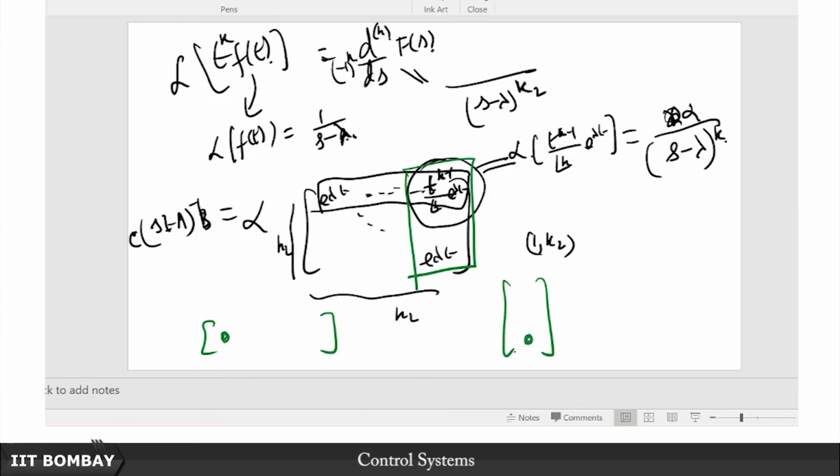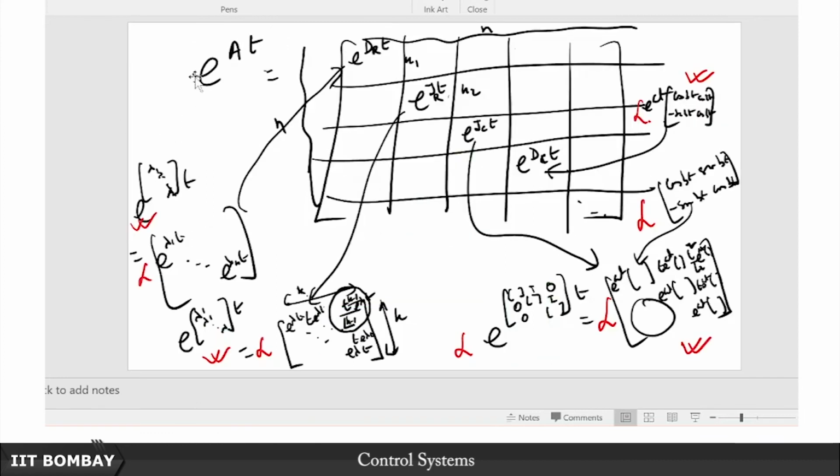That reminds us of the exact same condition we had for joint observability and controllability. So we have verified that for this block the conditions for joint observability and controllability need to be satisfied in order for it to be minimal. So if you are realizing it in the minimal fashion, it must be jointly controllable and observable. For this block also we have now checked that if you want this to be minimal, then it must be jointly controllable and observable.